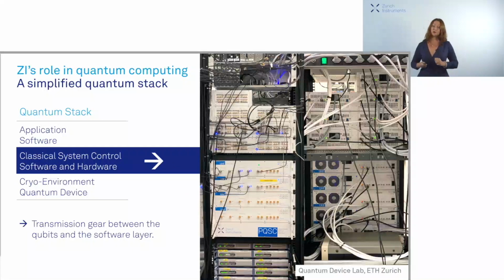Now, we want to connect the qubits with the algorithms. We have the hardware, kept at the temperature of tens of millikelvins. We have the software, and between them there is the interface, which is exactly where you can find Zurich Instruments. We have arbitrary waveform generators, quantum analyzers, and PQSC. This quantum stack in the picture is built at ETH in the group of Professor Andreas Wallraff, and it can control 20 qubits. Controlling qubits requires analog signals.